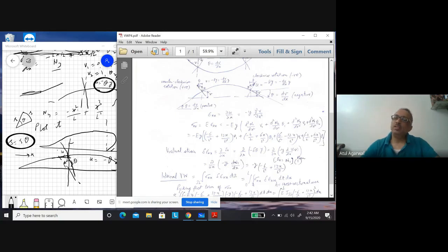We had earlier seen that vertical displacement is nothing but N1 v1 plus N2 theta 1 plus N3 v2 plus N4 theta 2. These are nodal variables, which are not changing with x. So you have to only differentiate the shape functions. We can put back the values of these derivatives. So we get stress as this.